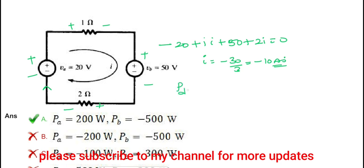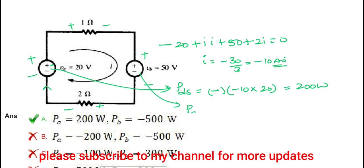So power delivered by the source is equal to, we'll put a minus sign first, minus of current minus 10 into voltage 20, which is nothing but 200 watts. So this is given by the source. Now power delivered by the second source is equal to minus of, now here the current is entering at the positive terminal, so it acts as a passive element.